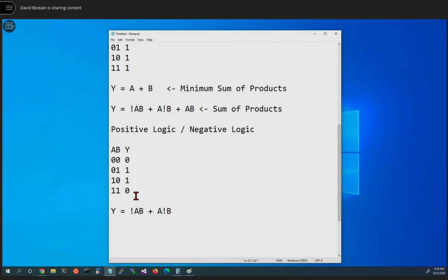Now this has a kind of higher abstraction thought about it, which if you thought of it this way, this produces 1s when the inputs are different. Produces false when the inputs are the same. So you can imagine this being used in some sort of a comparison circuit where we're trying to identify whether something is different or identical. And of course, we would expect that there is a function looking like this.